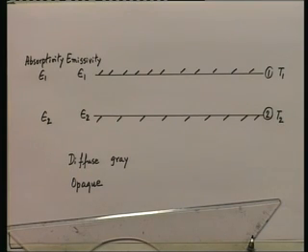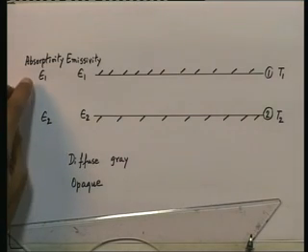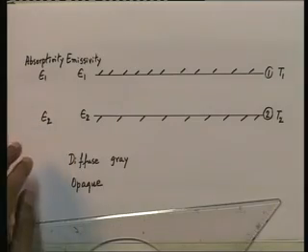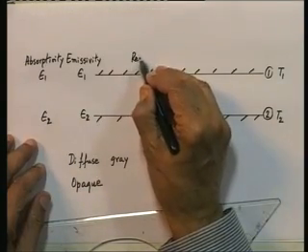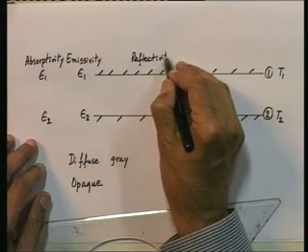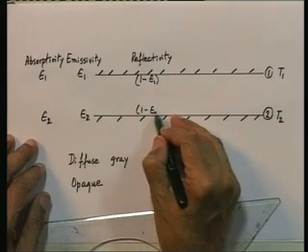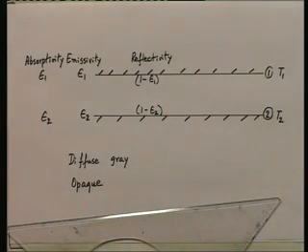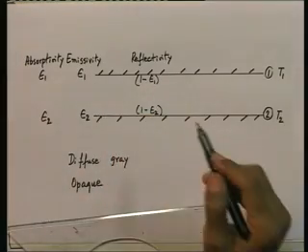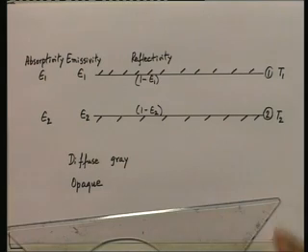If they are opaque, it follows that the reflectivity of these surfaces will be 1 minus epsilon 1 and 1 minus epsilon 2. So, let me write that also. The reflectivity of these two surfaces, this one will be 1 minus epsilon 1, this one will be 1 minus epsilon 2, because they are opaque. Therefore, absorptivity plus reflectivity must be equal to 1. So, this is the characterization of the surface. A two surface enclosure made up of two infinite parallel plates, diffuse gray surfaces, opaque surfaces, maintained at temperatures T1 and T2. Emissivity and absorptivities are epsilon 1 and epsilon 2. Reflectivities are therefore 1 minus epsilon 1 and 1 minus epsilon 2.